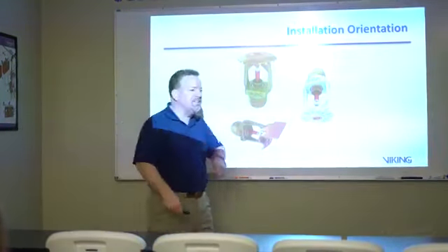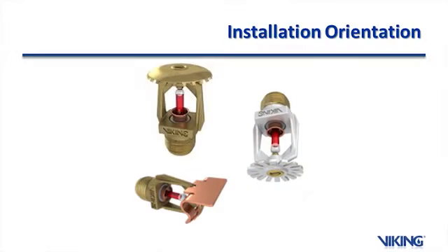I'll tell you, a perfect example of that is in a hotel room. I'm using it in a hotel room to save piping, basically, going into the hotel room, and maybe I don't have the capability of going through, you've got concrete floors, right? And you don't have any room to move in your concrete floor area to put a sprinkler in the middle of the room. So instead, they bring the piping in from the corridor, pop one in the bathroom, and then pop another one right out, protecting. You'll see that a lot.